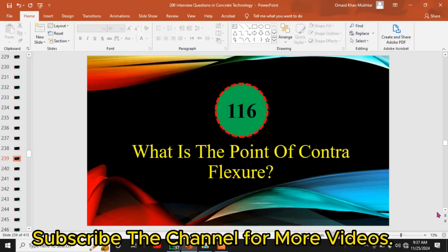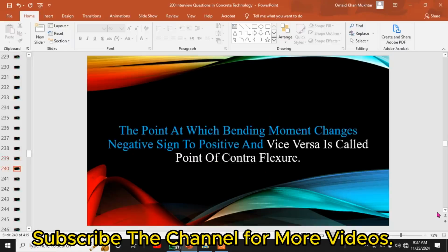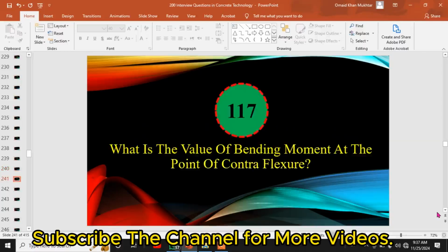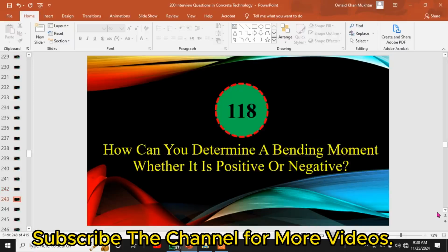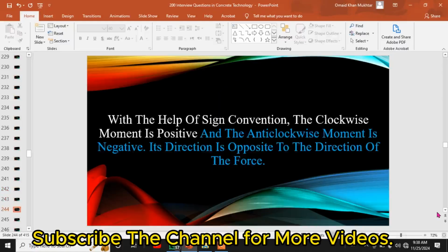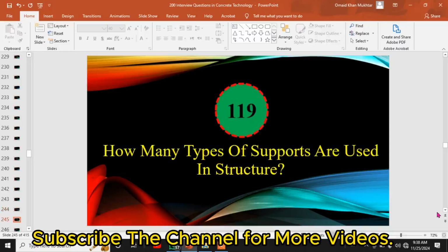116th. What is the point of contraflexure? The point at which the bending moment changes from negative sign to positive and vice versa is called the point of contraflexure. 117th. What is the value of bending moment at the point of contraflexure? The value of bending moment at the point of contraflexure is 0. 118th. How can you determine whether a bending moment is positive or negative? With the help of sign convention: the clockwise moment is positive and the anti-clockwise moment is negative. Its direction is opposite to the direction of the force.